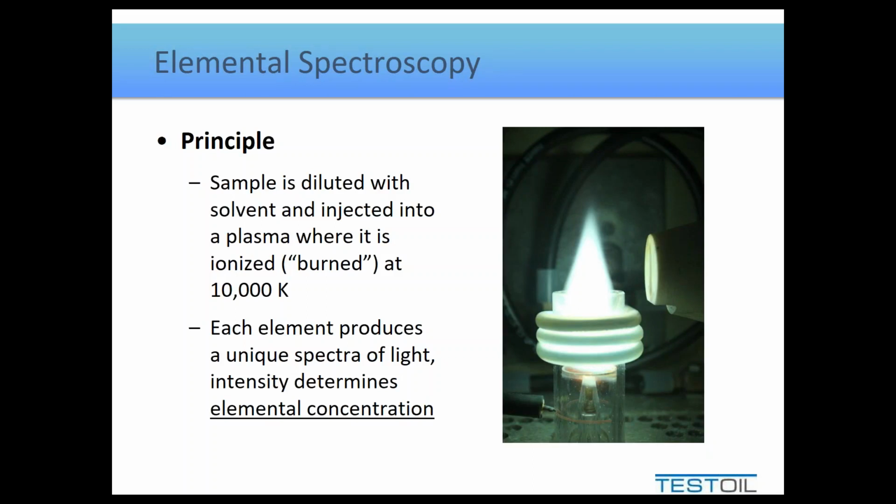So when we have something like, say, Babbitt wear, we won't see Babbitt show up on the report, we will see lead and tin show up on the report. However, if we have brass or bronze wear, both of those contain lead and tin, the differentiator being they will also contain copper. So when we see something like lead and tin on a report, we always look for the correlation to what other metals might be present. Like I said, if copper happens to also be there, we can now enter into consideration like brass or bronze.